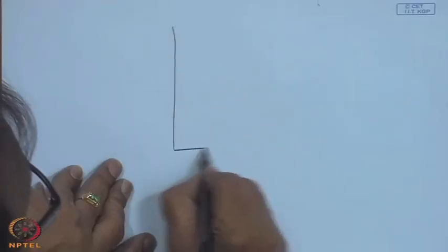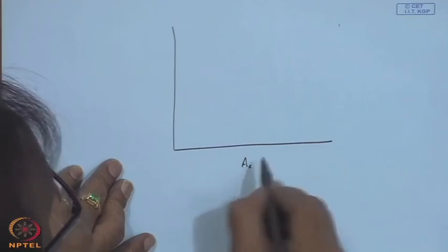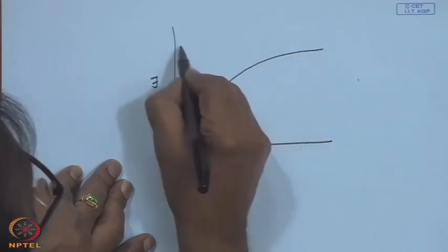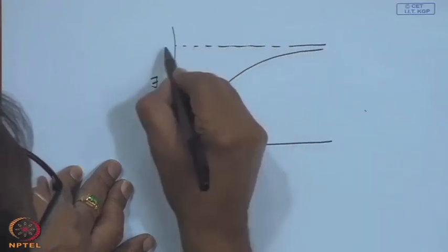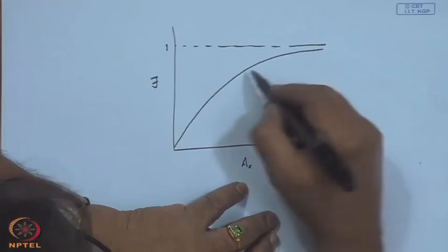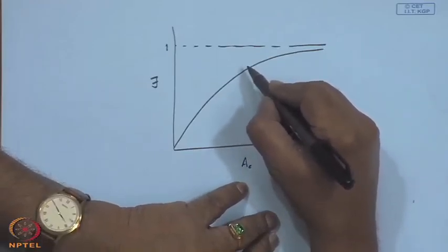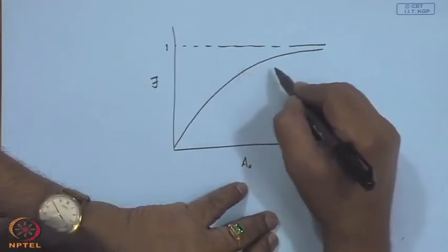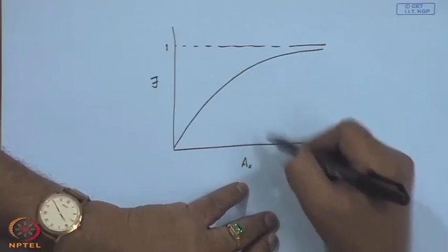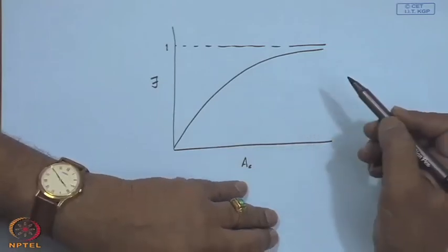That is, ultimately by making 12 monthly calculations, we are in a position to get area versus solar load fraction, something like this. This is unity, and I can do whatever optimization or whatever studies one likes to have by changing the system parameters, either the storage or the flow rate or the heat exchanger size, location, area of course is the main thing, and collector parameters.